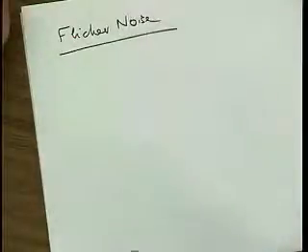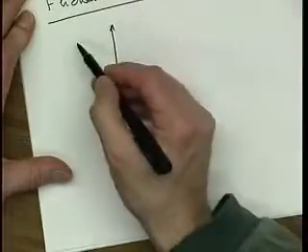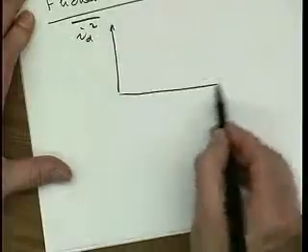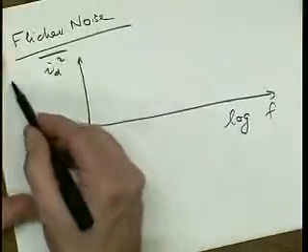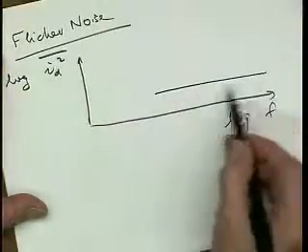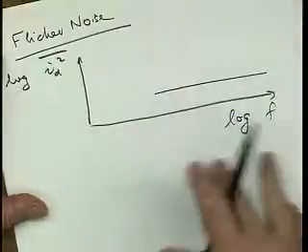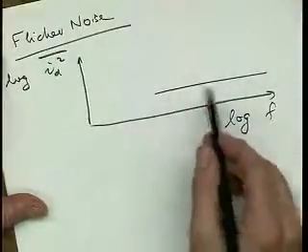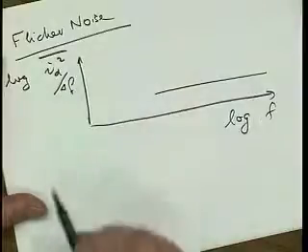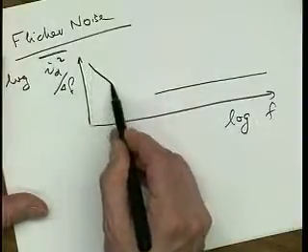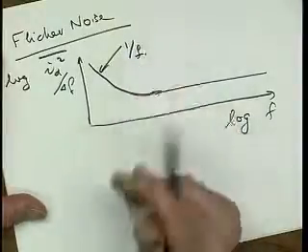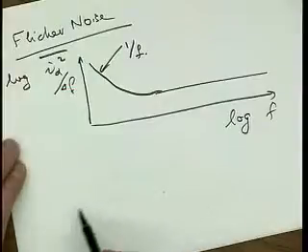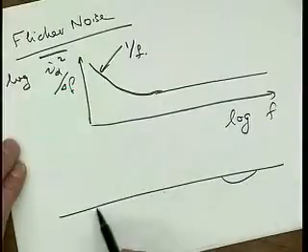Turns out that if we were to somehow measure, and we're going to do that afterwards with SPICE, the noise current of our MOSFET as a function of frequency, and we do this log scale, here also log, then we would get here this 4kT 2/3 gm delta F. But at low frequency, you would find that we get excessive noise, and this excessive noise at low frequency is called 1/f noise.